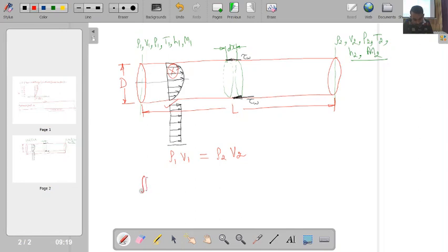As per the integral form, I have the surface integral of rho v vector dot dS vector, and then because I want to write this momentum equation only along this single direction, say this is my positive x direction, along the x direction because I am considering the situation of 1D flow, I will take over here the x component of this multiplied with velocity in x direction.